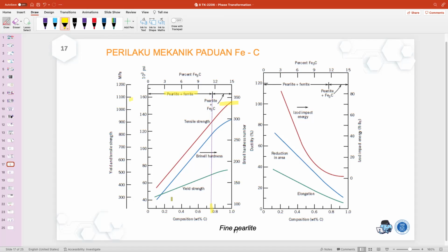Okay, so it is very much different. For example, this one, hypereutectoid steel, is for gears from machineries, very strong tools. But in here, for example, maybe the hypoeutectoid steel is good for appliances, for the body of electronic casing, or for a pipe with a lower schedule number, only for atmospheric pressure. You can see the difference between these.